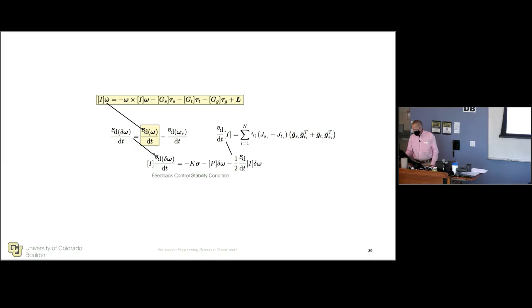So once you have this times this inertia tensor, you notice we used here I, the total inertia. So in that Lyapunov function, I is not just a constant anymore, but it is what it is. The convenience is I will have an I times omega dot, which means I can plug in my equations of motion. And these are actually convenient, written out this way, because I have everything that I need to directly plug in for n variable speed CMGs, right?